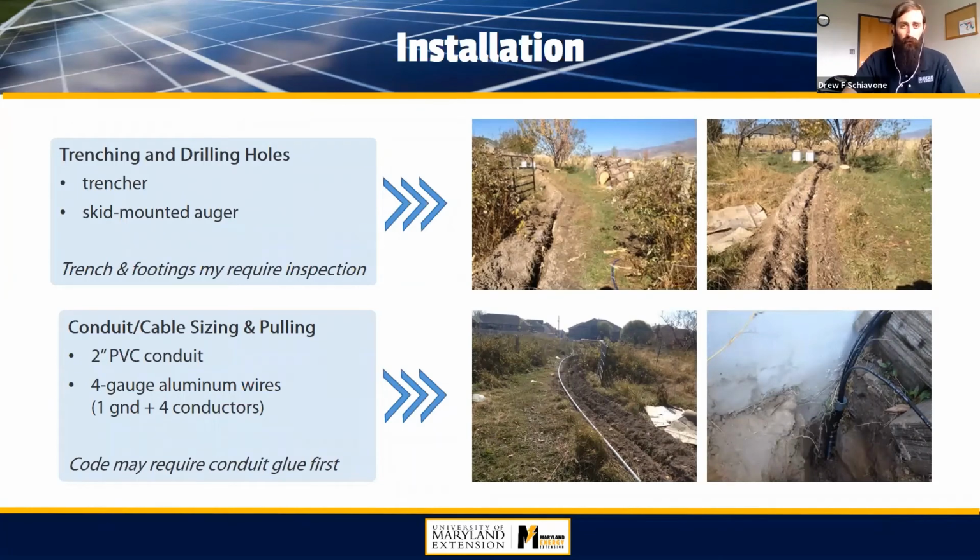And every PV system is going to look a little bit different, but those cables are running all the way back around 400 feet back to a large string inverter. You could use microinverters as well. There's just a little more expense. In this case, the single series inverter was already on hand, so that's why this system was designed as it is. But it's going quite a distance to cover 400 feet back to the inverter. So that's just how this project worked out.